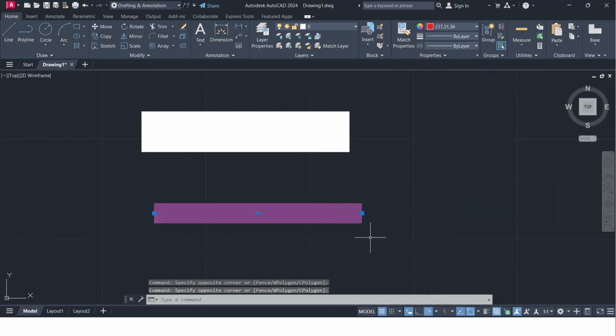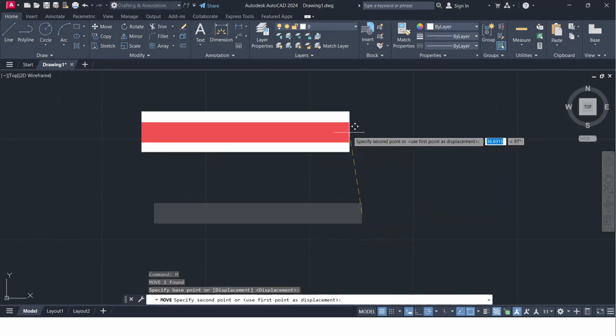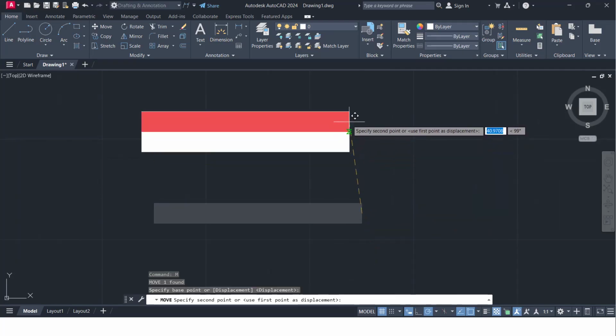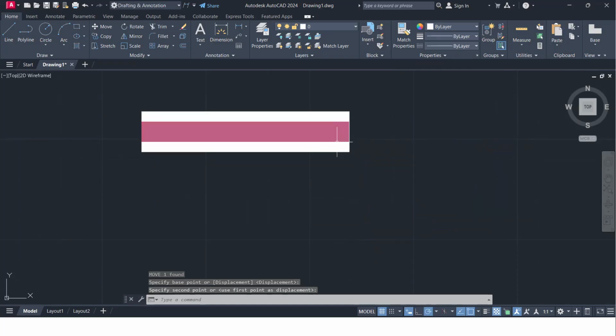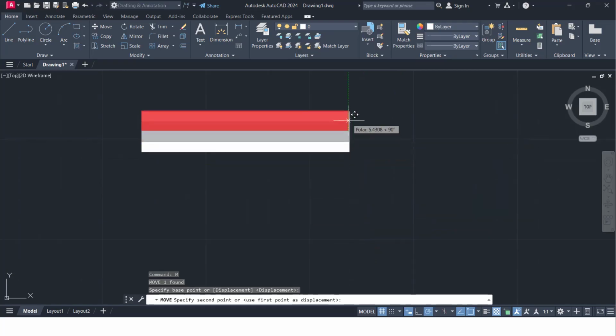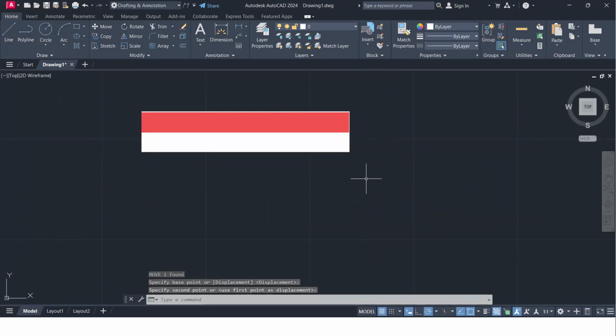Okay, come to this part and I hit enter first, and then I put this part here, and this looks like a half portion of this part, right? Okay, this looks like a half portion of this part. That's clear. So this is called a half width and single width, both work the same. But for half width, we have to double this width, and then the total width of this line is 20 mm. But this line is 10 mm only. This is the simple difference between them.